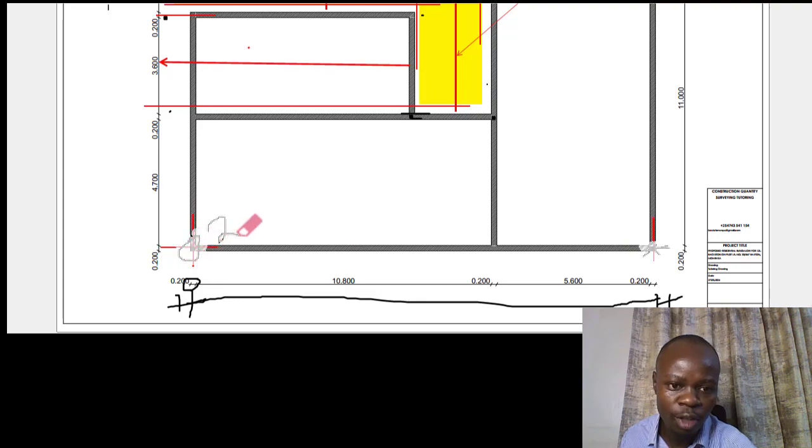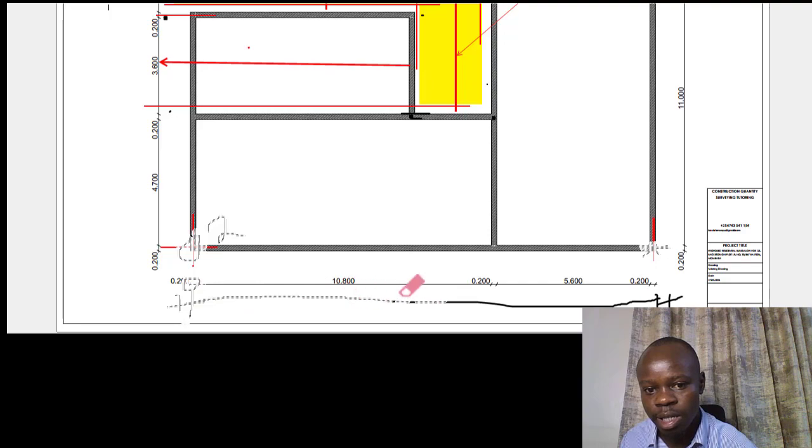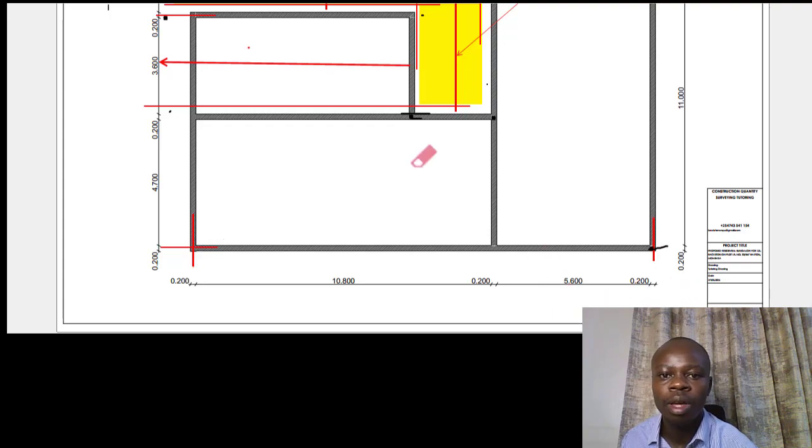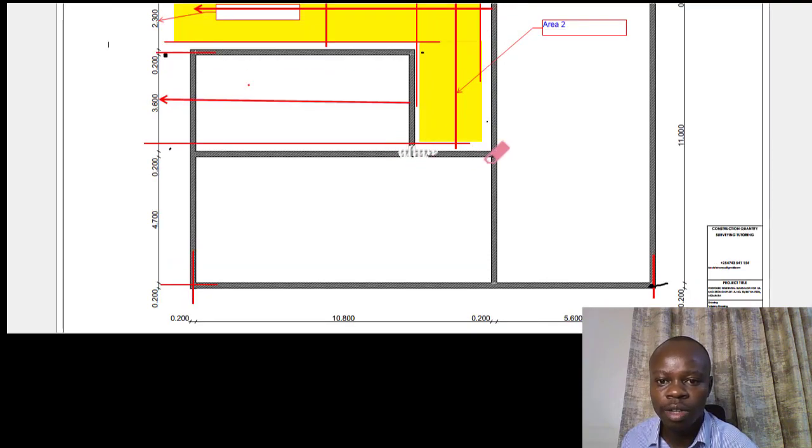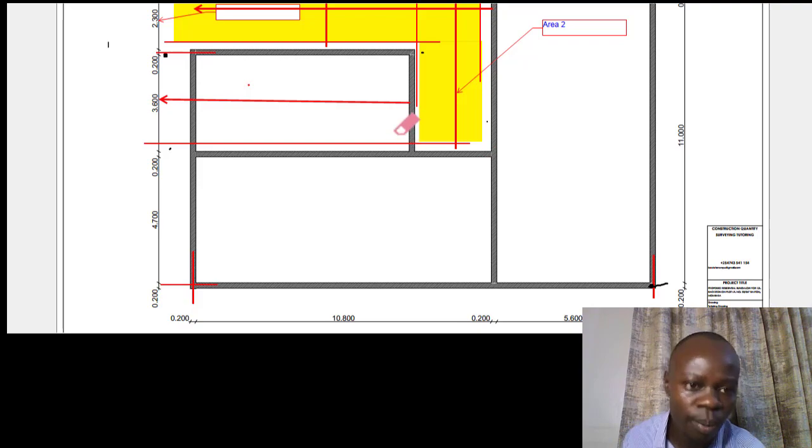That is the length plus width times 2. After that, you also add the recesses. You add the lengths for the recesses in the manner that they're also from the external faces of the wall. That is, from this side, the way we have it here is 3600, but then you add 200, and 200 is up to the point where you have the face of this particular wall.